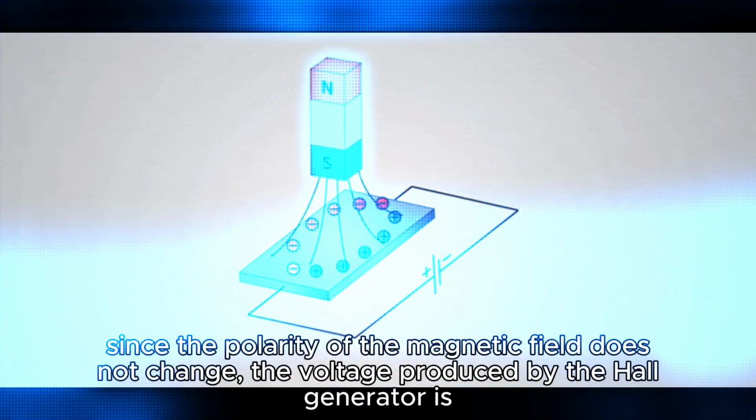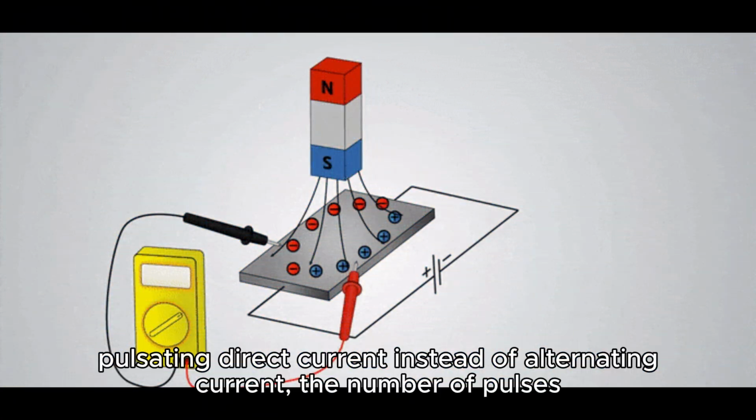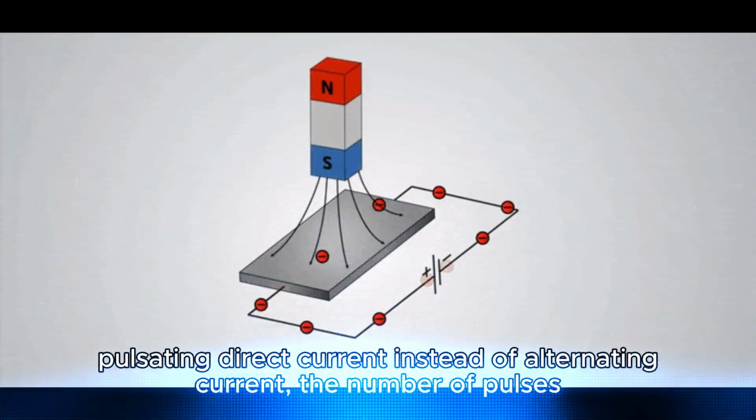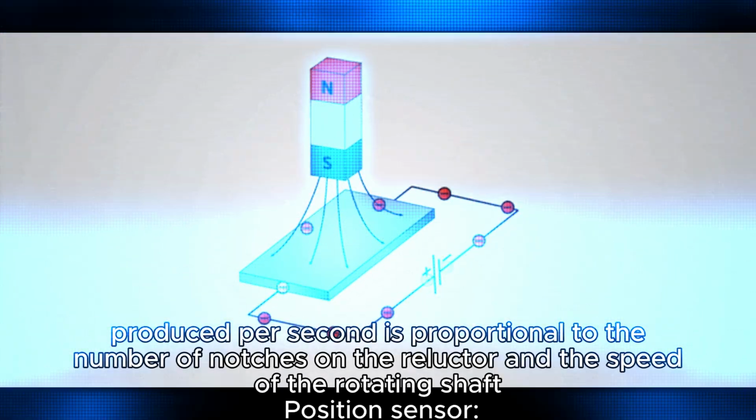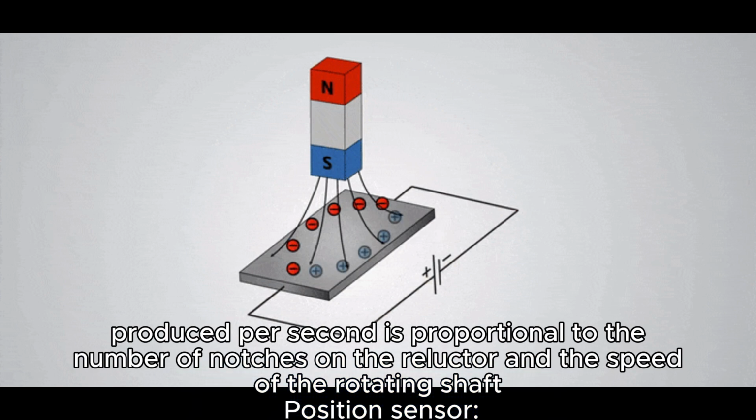Since the polarity of the magnetic field does not change, the voltage produced by the Hall generator is pulsating direct current instead of alternating current. The number of pulses produced per second is proportional to the number of notches on the reluctor and the speed of the rotating shaft.